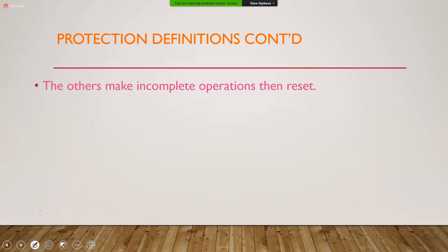So in other words, if the local breaker takes care of the problem, they will say, okay, fine, problem is taken care of, we'll continue to operate and keep the system intact. But if the assigned breaker does not operate, then they will operate and more of the system will be lost. Okay? All right. So we talk about time graded, so that they are based on determining whether or not the relevant breaker will operate. That's time graded. Good?